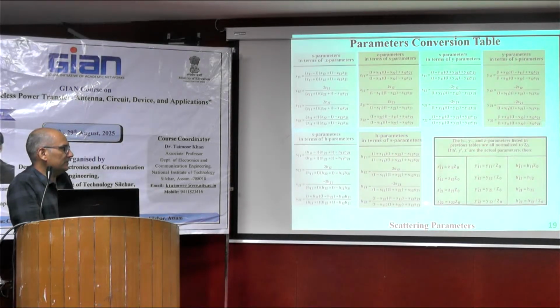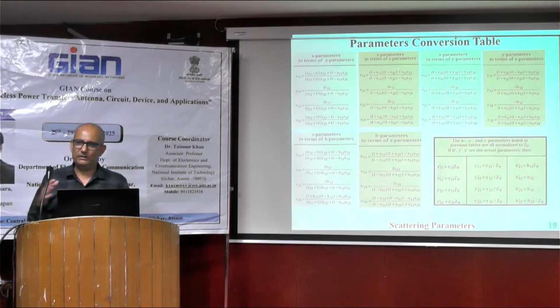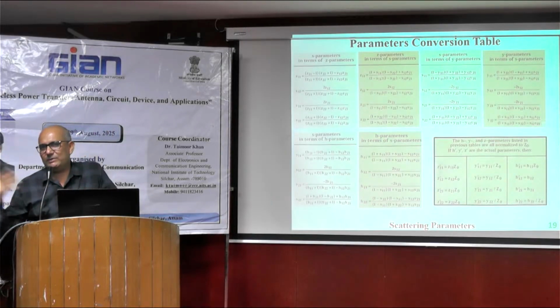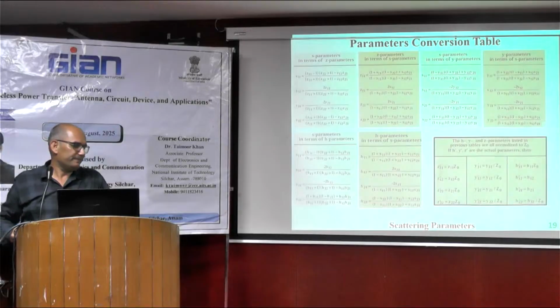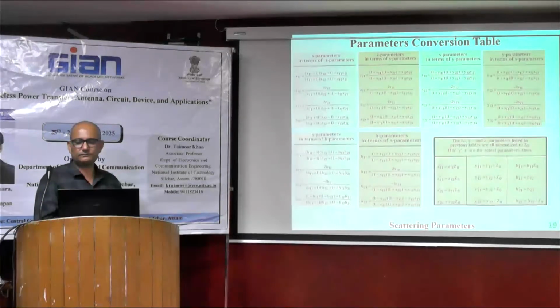By using this, the conversion will take place automatically. Other than S parameters, the rest of the conversions we always prefer at low frequencies: Z to Y conversion, Y to Z, ABCD, and so on. But because we need to have the entire discussion in S parameters, that conversion is also equally important for us.